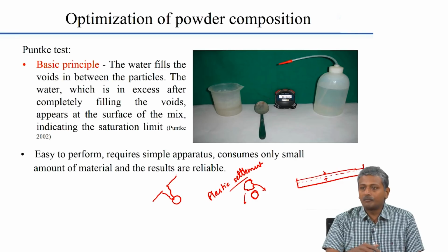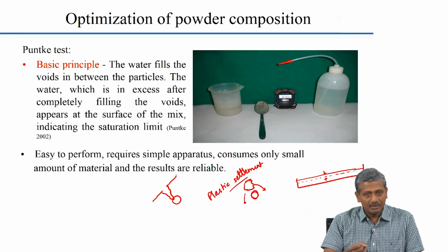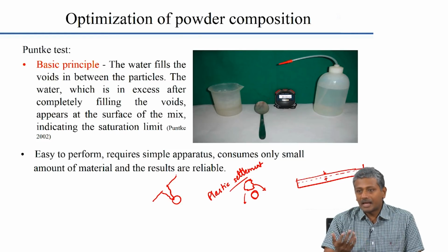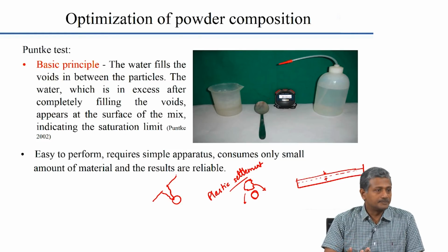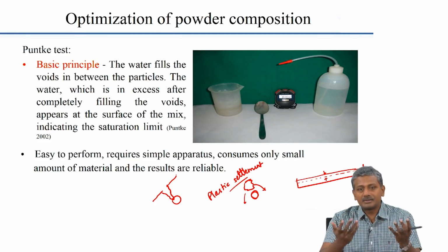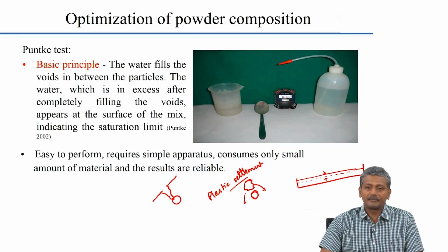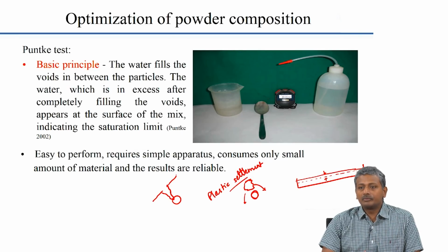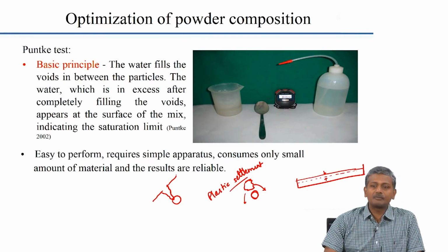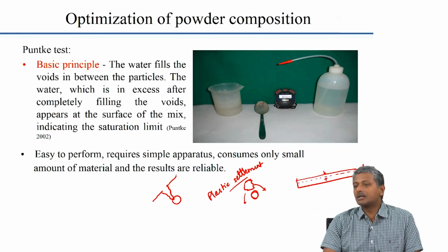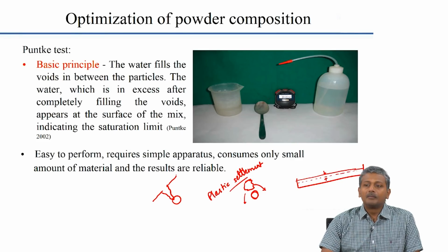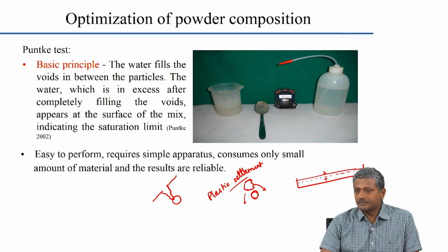If you pour from the top, one, you have the risk of segregation, the other is that you can create air gaps inside. Okay. So, now in a column, having a high slump flow may be quite useful. Secondly, there is no danger of plastic shrinkage or settlement because it is entirely enclosed, there is no problem there, right. So, the design of self compacting concrete would be specific to the type of situation that you have. The characteristics of SCC desired may depend on the kind of structural element, but of course, you also have the requirement of the strength.